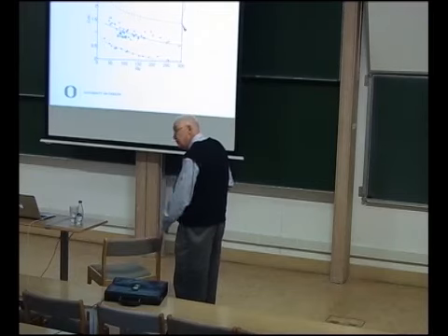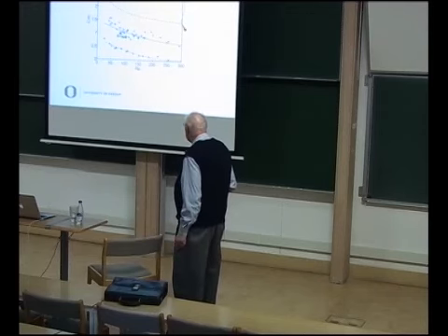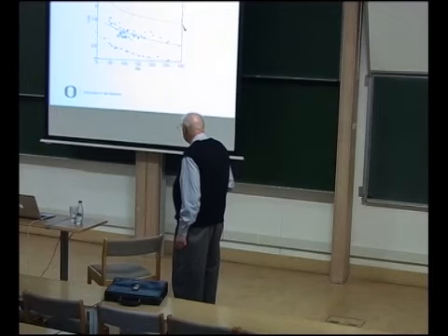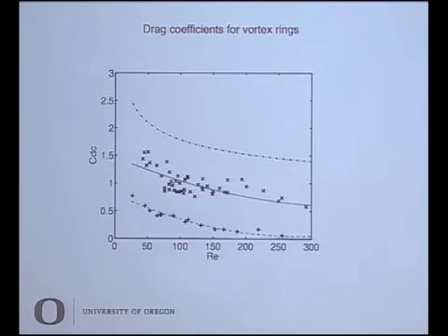Now, here's the drag coefficient for the one you see in all the textbooks for a circular cylinder in a linear flow. And the X's are experiments done with my old gun with the rack and pinion drive. And you can see that they certainly do decrease with Reynolds number, which is more or less what one would expect.